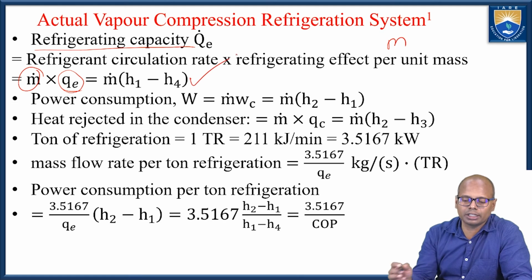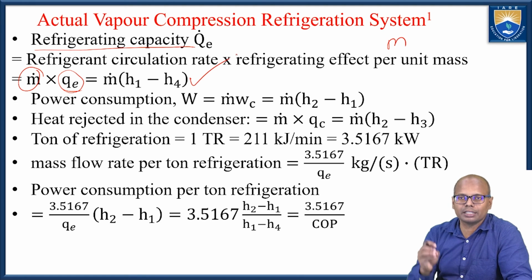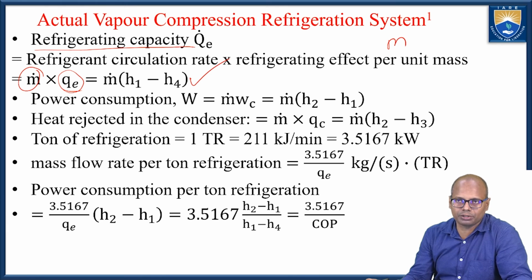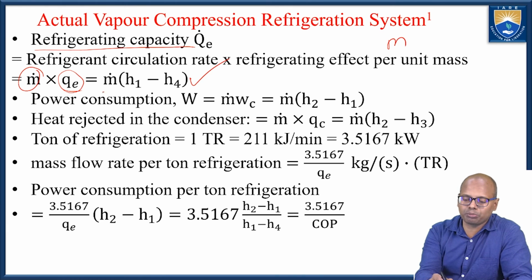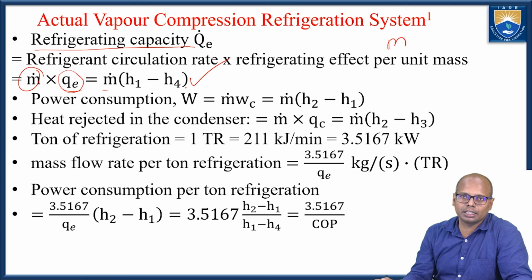I can find out the refrigerating capacity of this vapor compression refrigeration system. So if I multiply these two, I will get the refrigerating capacity of this VCR system.